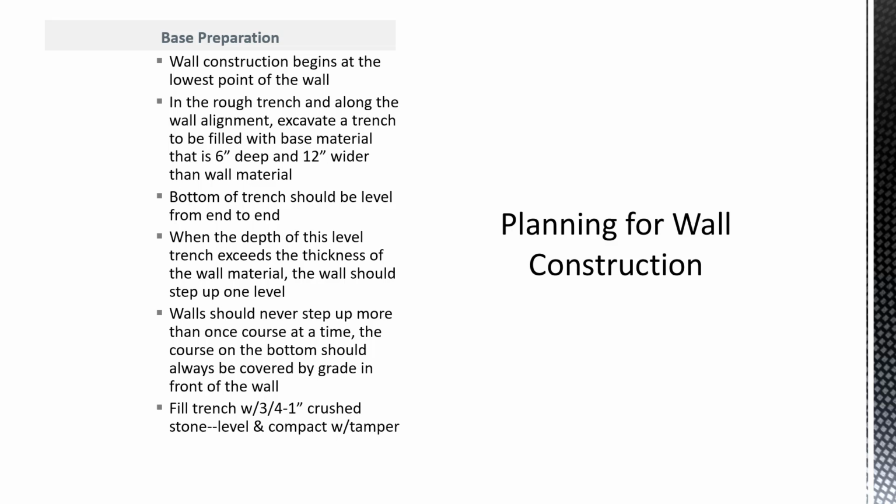Now, I've seen walls that don't do that. Those are a disaster waiting to happen. And then fill the trench with 3/4 to 1 inch crushed stone, level and compact with the tamper. That is going to be your footings or your footers for your retaining wall.